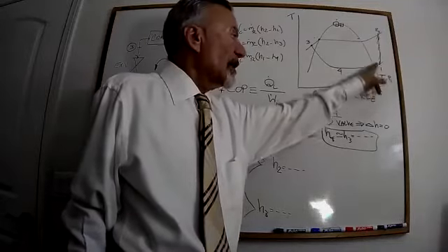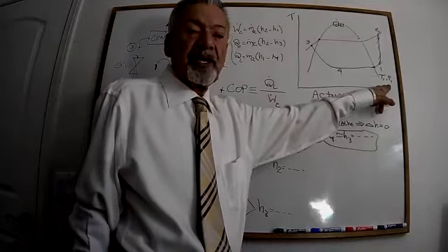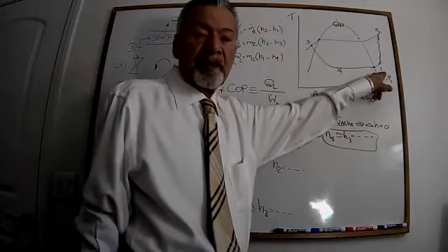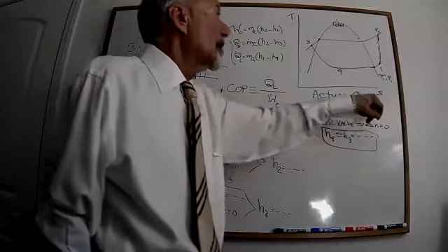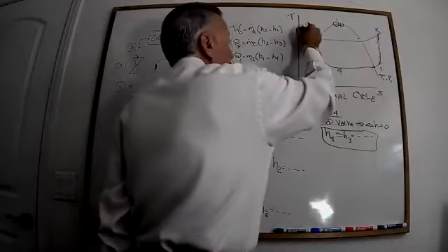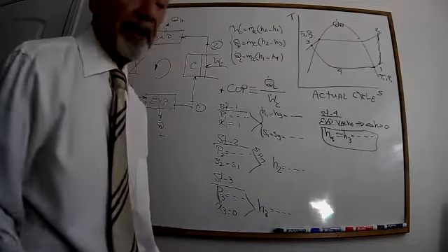The only way you can find that value is to have those two reference points, pressure and temperature, to find the value H1 as a superheated. Similarly, here you have to have temperature and pressure at point 3.